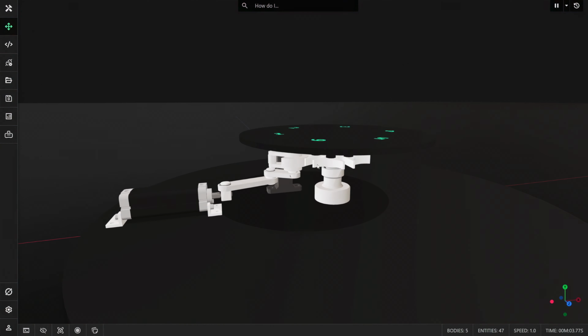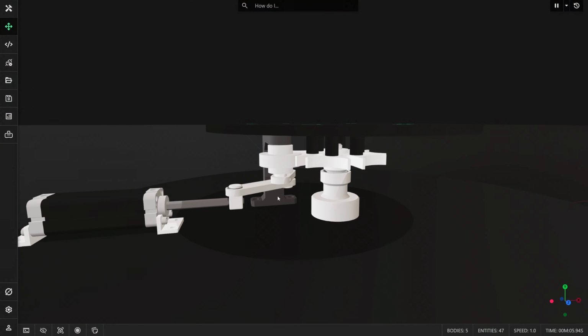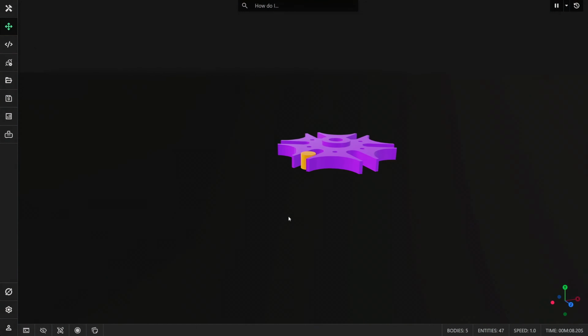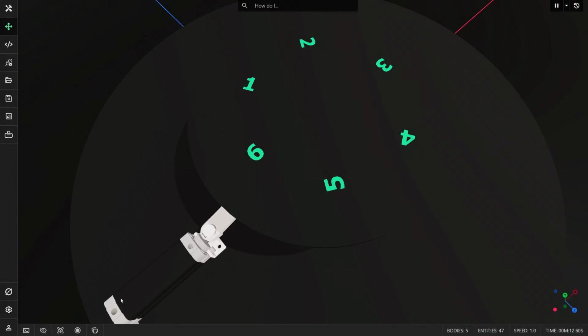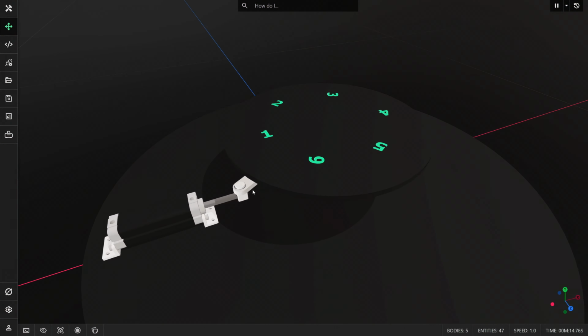The back and forth movements of the prismatic joint translate into a continuous rotation of the rod. This then gets converted by a Geneva mechanism into a controlled intermittent rotation of the wheel for indexing the table.